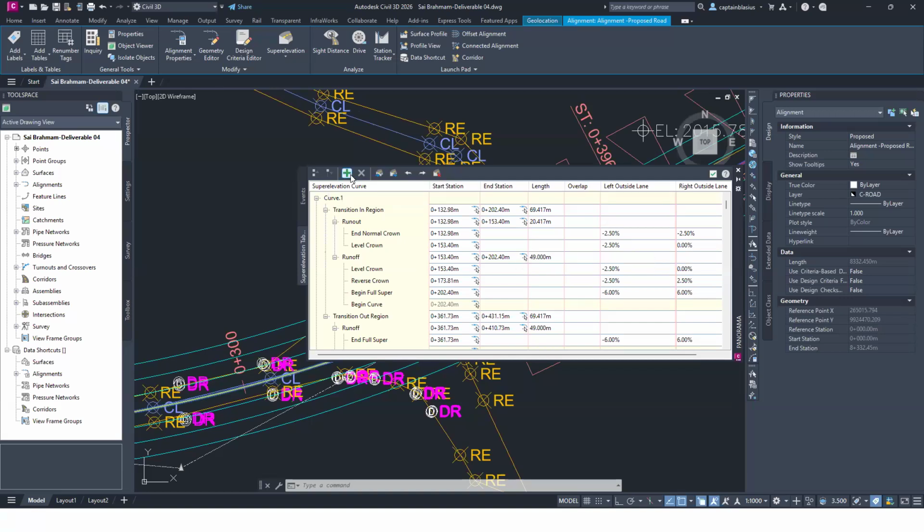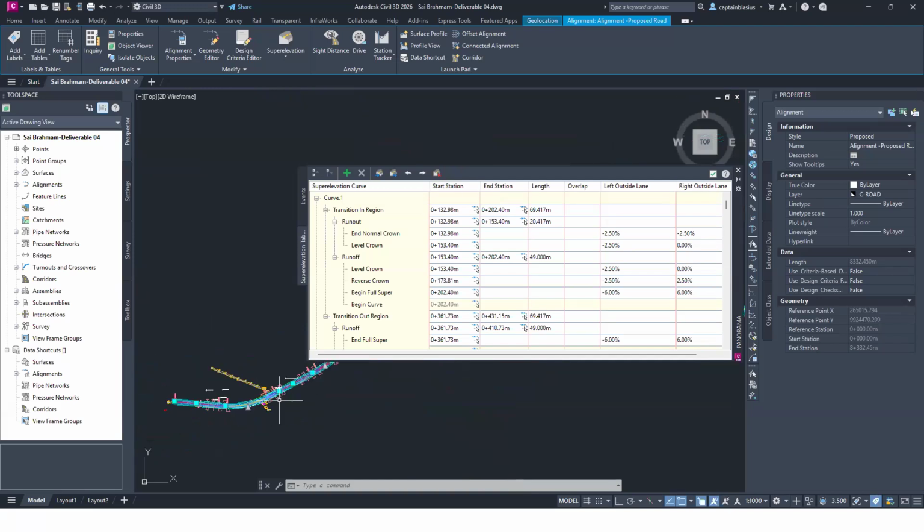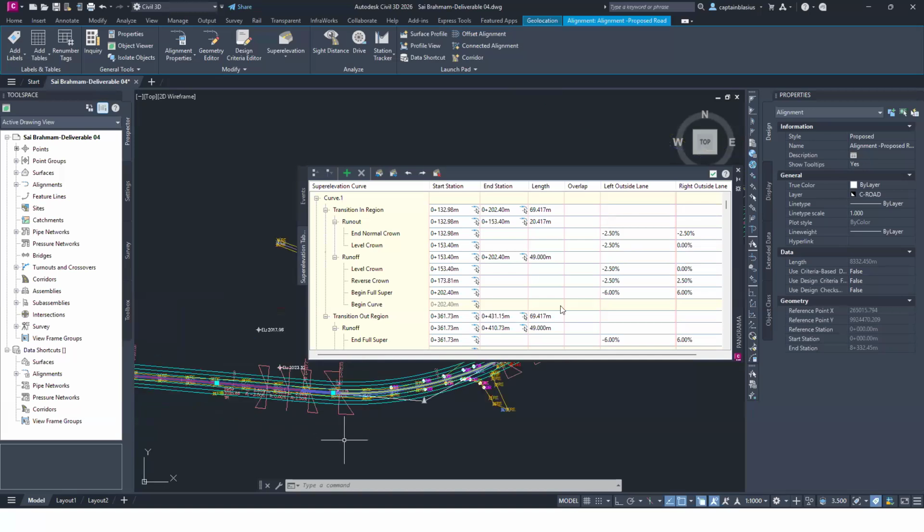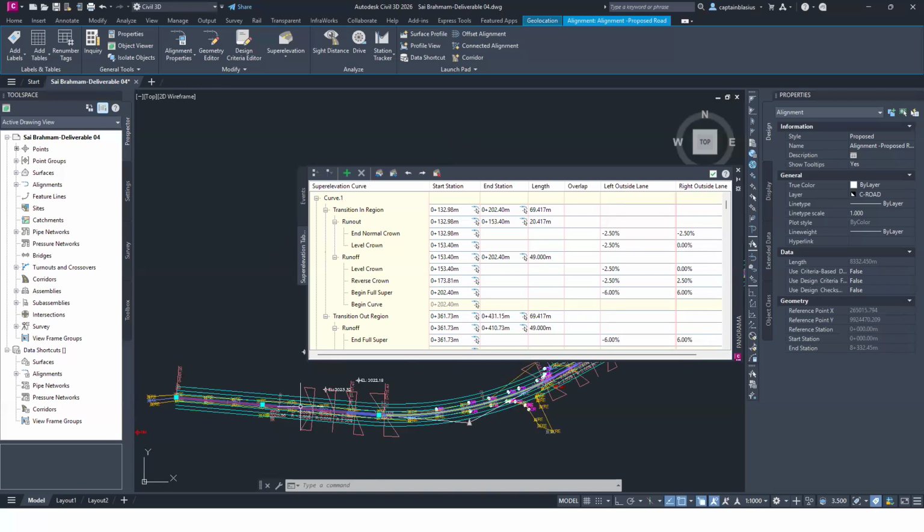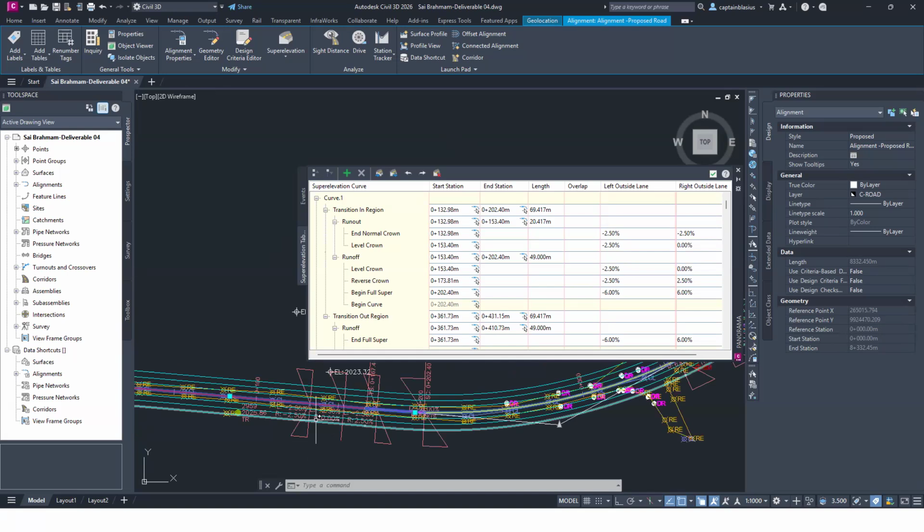When you go to the next one, where you're having the addition sign, this is for adding a super elevation critical section. What do I mean by that? Let's say you've assessed your super elevation and you find that for some reason you're missing a section. And just before I go to these tools right here, let us look at this. You can see at this point that already you have the super elevation labels. So this is what we call the super elevation labels.